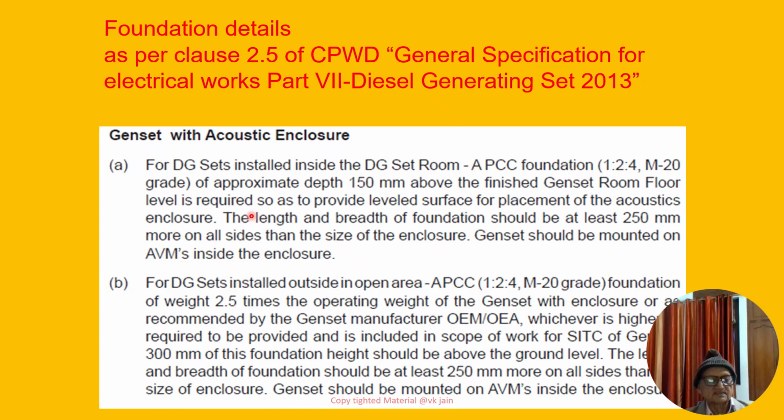The length and breadth of the foundation should be at least 250 mm more on all sides than the size of the enclosure. The generating set should be mounted on AVM inside the enclosure.